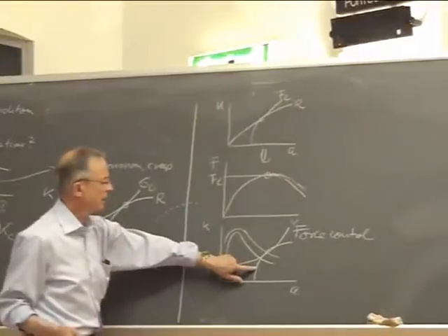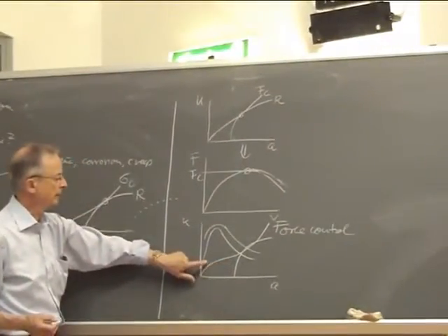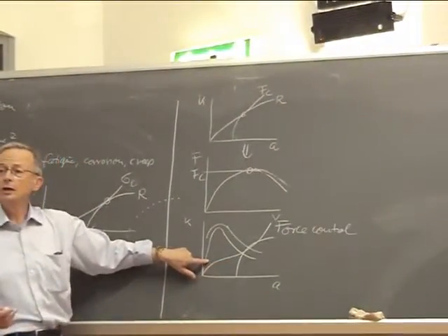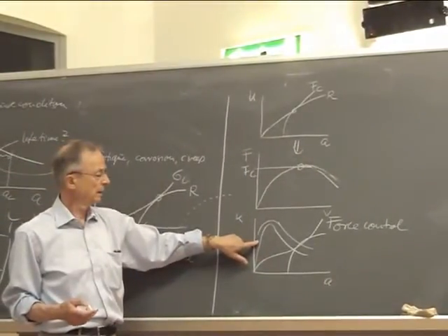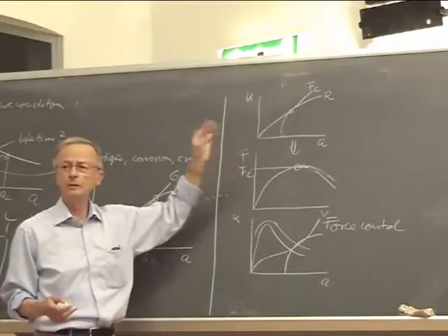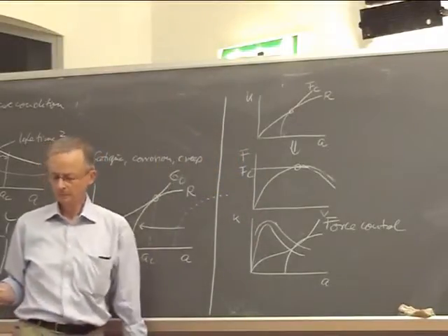And this also shows that even under displacement control with a very stiff machine, the specimen can become unstable if the crack is very small, very short. You see, would I shift the R curve far to the left-hand side, I would reach tangency condition. So I've never seen any kind of textbook. They all come from above, from heaven, you know.